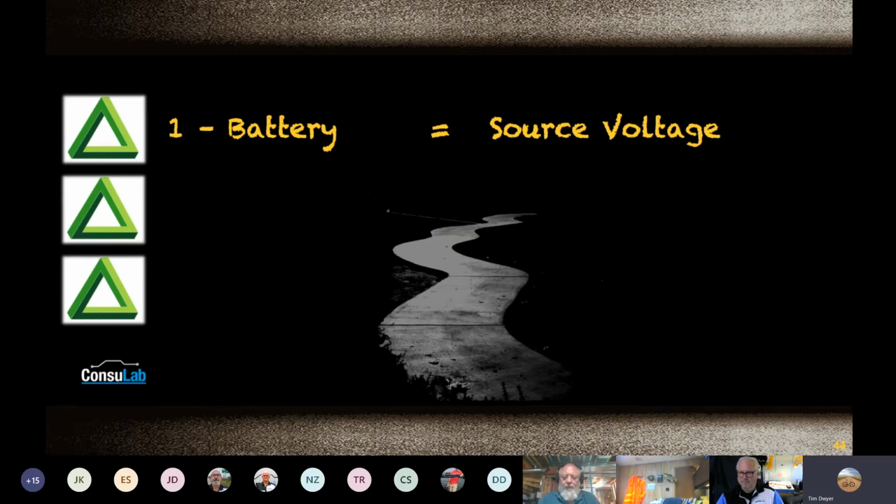So if we have a circuit, and today the most simple one is a switch and a light bulb. If we have a light bulb lit and we want to know if it's functioning as designed, as engineered, as efficiently as it can, where would be the next place to test? And we're talking voltage here. Well, I want to go to the load. I want to go to the thing that's the trouble.